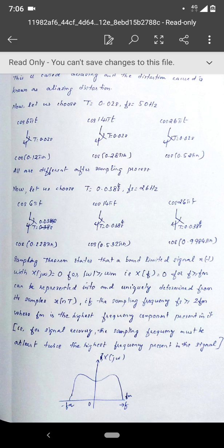Okay, so you can see that here Fm is the maximum frequency component in that composite signal. Earlier we have seen a composite signal where the maximum frequency component was 13 hertz. So here, from the frequency spectrum, you can see that the maximum frequency component is Fm. This Fm determines the sampling rate, like 13 hertz determined the sampling rate. In general, the Fm, which is found from the spectrum after finding the Fourier transform, will determine the sampling rate or sampling interval.